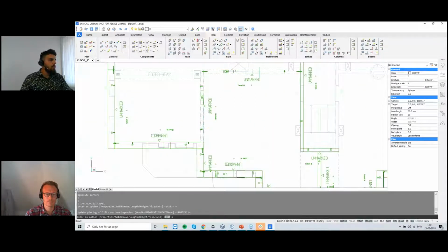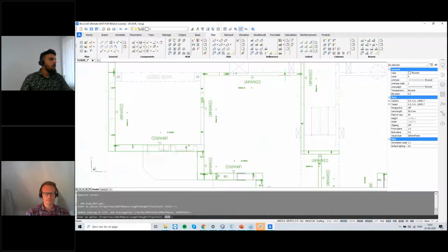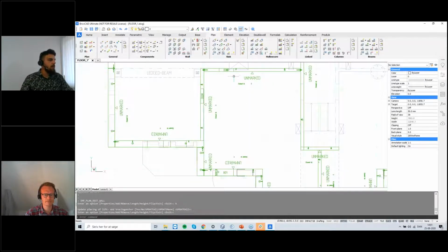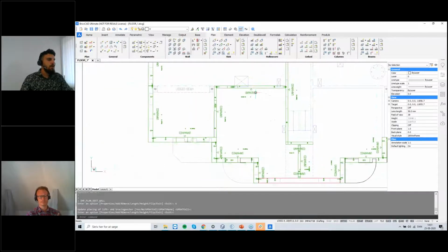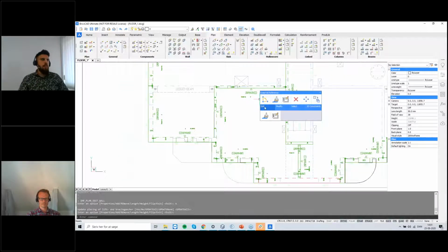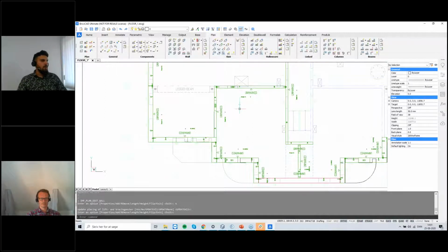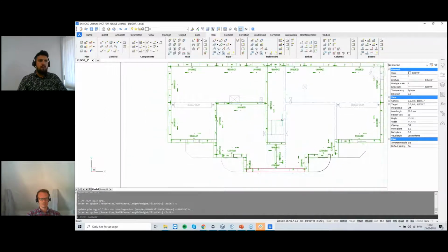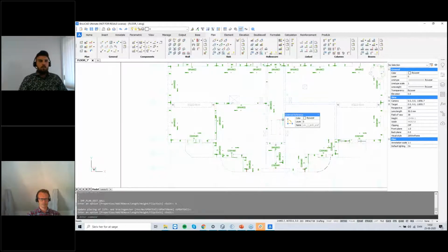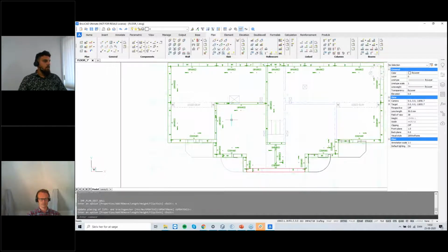Excellent. If you might notice, maybe you didn't, the lifters and the bracings were changed a little bit in position, because every time I make an opening, they recalculate the center of gravity, and they are placed according to the center of gravity. If you don't want to have automated lifters, we can take them away and you can place them yourselves, even though we always say that lifters are one of the most important things to do. So I have added some openings. I have added my casting materials, at least.